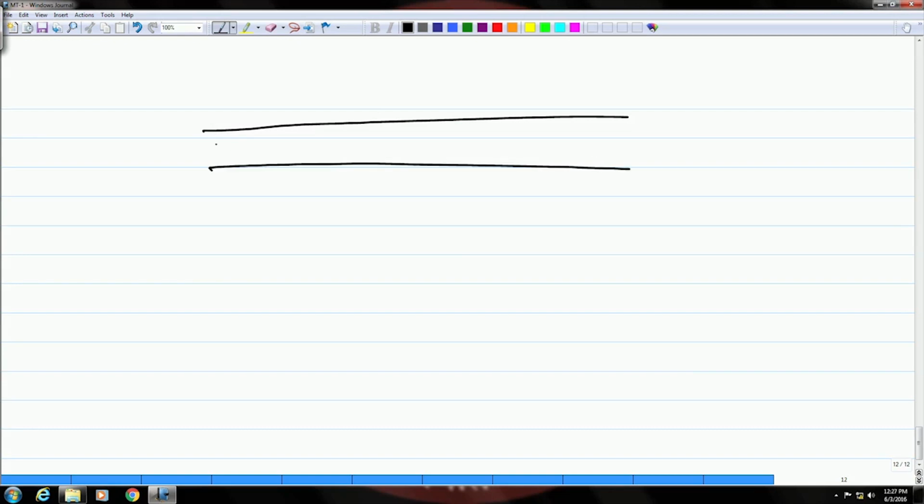So, if you see this table, for example, it shows the magnetizing current which is being applied to magnetize the part, and the minimum number of holes indicated by the magnetic particles.